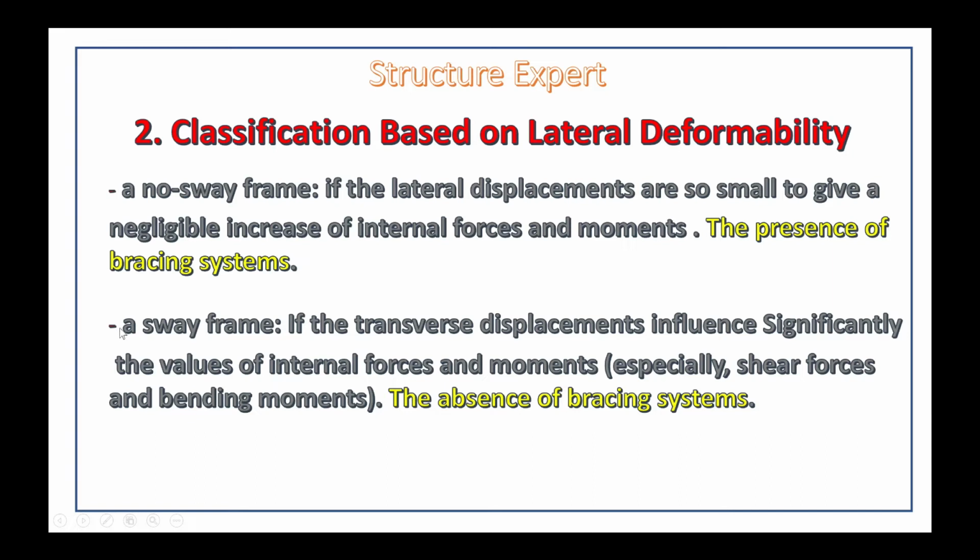And a sway frame is where the transverse displacement, the lateral displacement, influences significantly the value of internal forces. For the internal forces we focus on the moment and shear force.